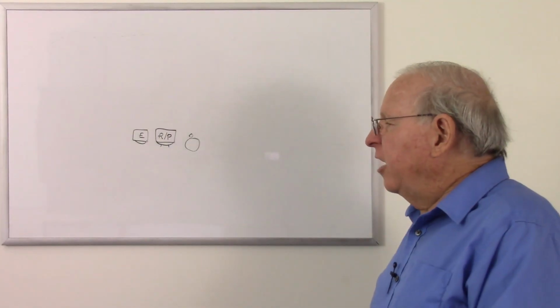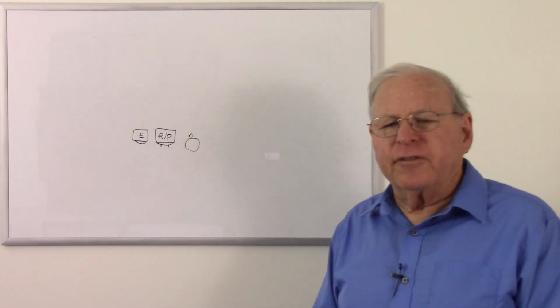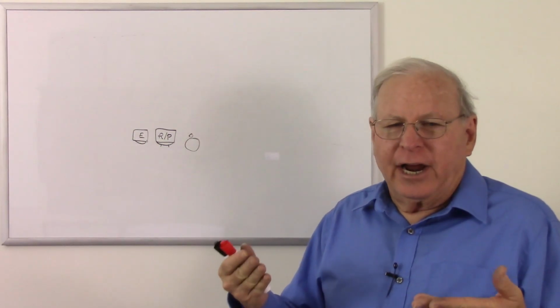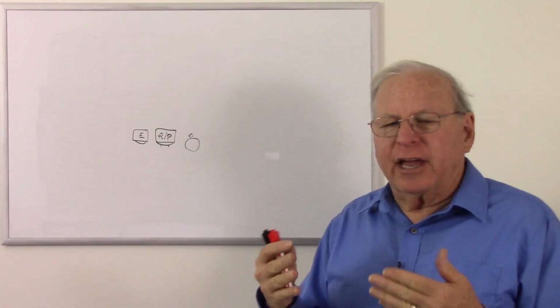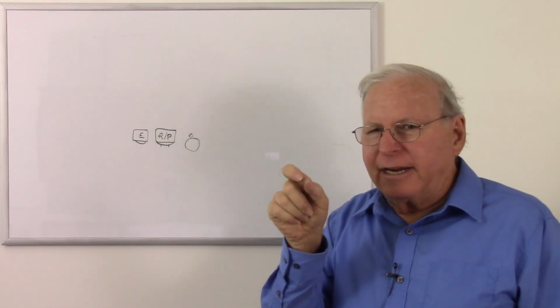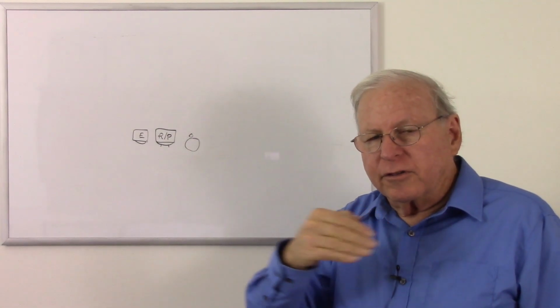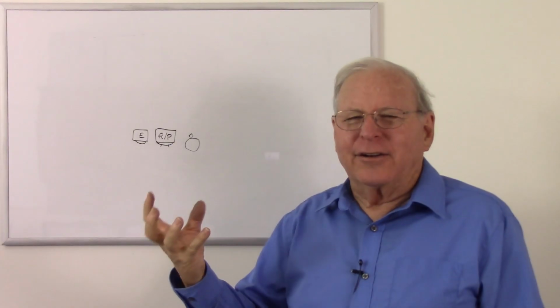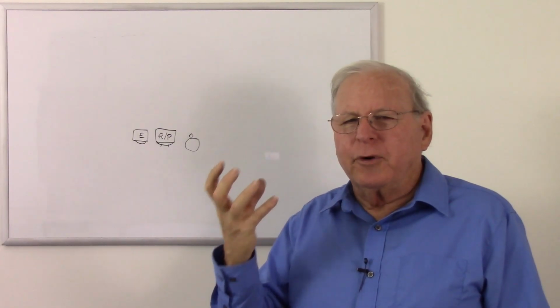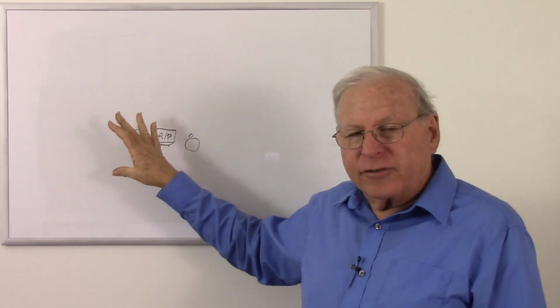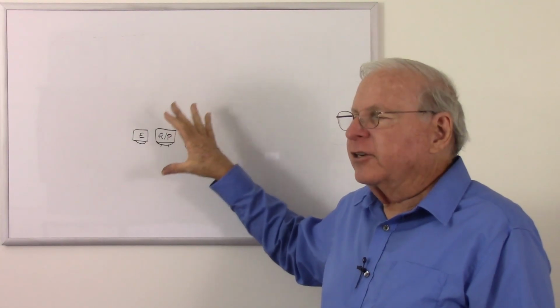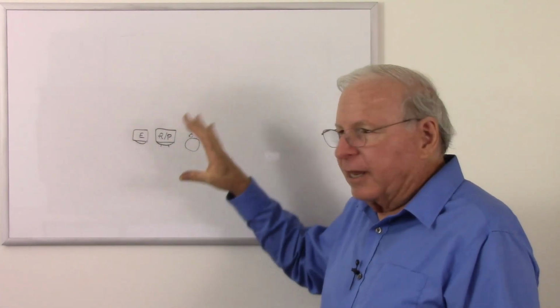And the last change was metal tape, where instead of using brushed iron oxide or chromium dioxide, they actually had metal particles, submicroscopic, tiny, tiny little particles of metal aligned along the direction of the tape. So we're kind of back to the wire recording where we're recording on pure metal. But with the proper bias, you could get even a better dynamic range and better frequency response with metal tape.